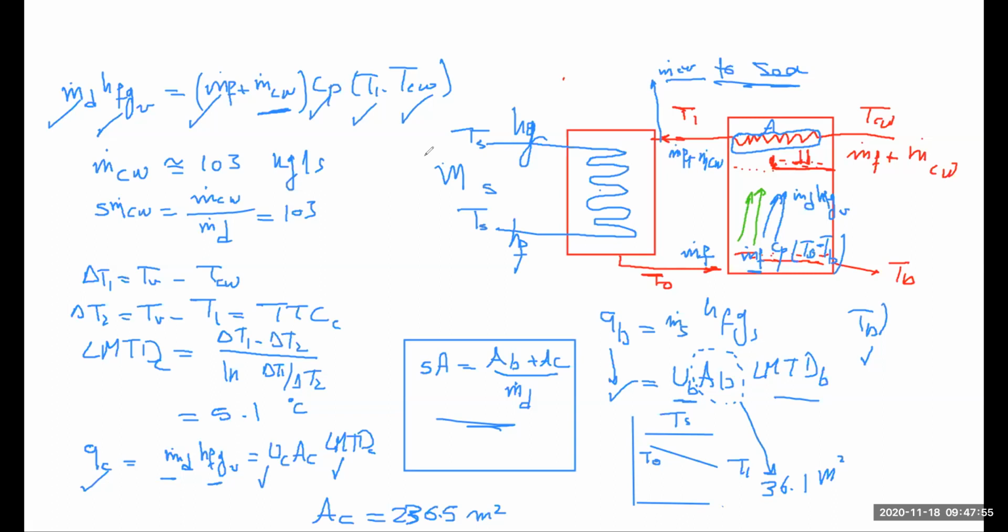All right, did I answer your question, Salah? Yes, one more question. Go ahead. The best tube for heat transfer is copper nickel. Yes, because copper has the highest thermal conductivity, but there's a problem with copper when it comes to seawater.